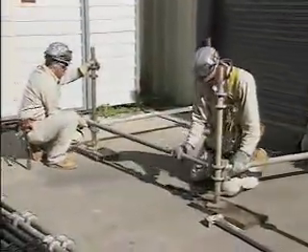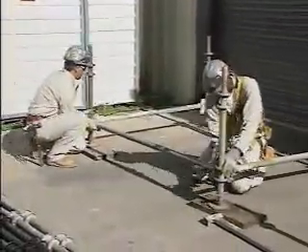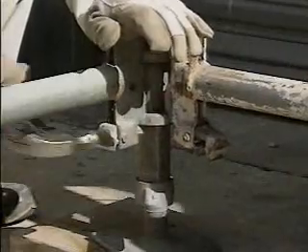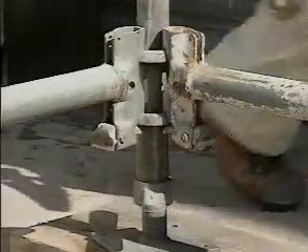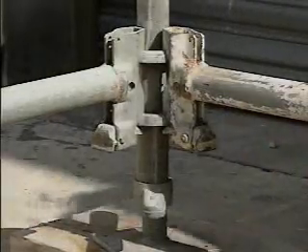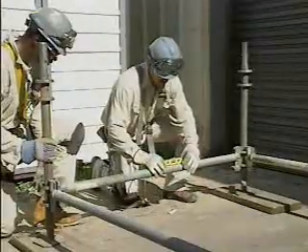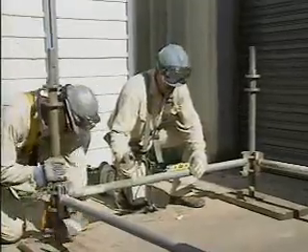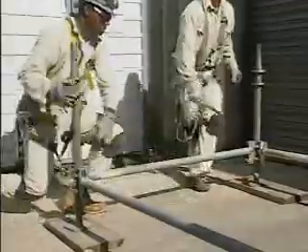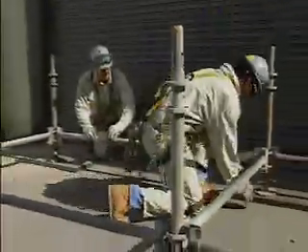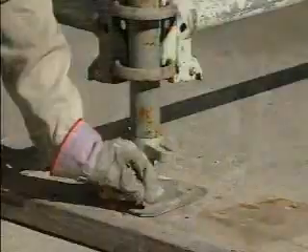Then, the first of the horizontal members are connected between the starter collars. The horizontal members are secured to the starter collars by driving in wedge pins on the end connectors. This locks the end connectors of the horizontal members onto the locking rings of the starter collar. If the scaffold isn't level, the builders adjust the screw jacks as needed to make it level. They check each horizontal member this way until the lower framework of the scaffold is level.